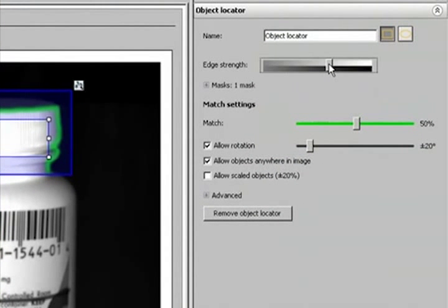And I will slightly loosen my tolerance again. With this, I can extend my match percentage to, let's say, 72%. My rotation, if it is one, I can allow my rotation to go all the way to 180 degrees if I want it. In my application, that is not desired, so I'm going to keep it pretty low over here.